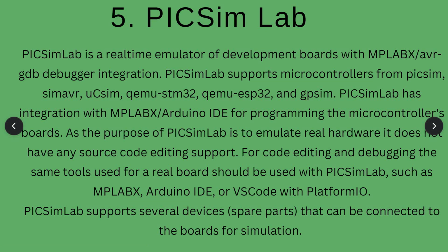So the next thing is Picsimlab. Picsimlab is an emulator development board with MPLAB X and AVR GDB debugger integration. Picsimlab supports microcontrollers from PIC, AVR, and other simulators. Picsimlab has integration with MPLAB and the Arduino IDE for programming the microcontroller board.